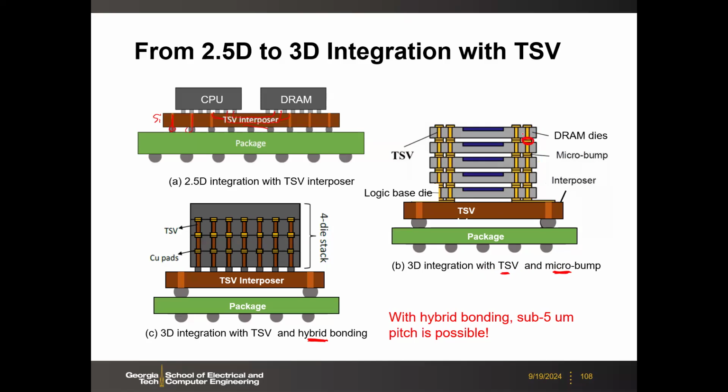If you have ever soldered your chip in your lab, you add some kind of alloy metal as a bond. Then you bond those chips. But in this case, this is micro bump. It's much smaller than what you manually do when you do the wire bonding in your lab projects. So this micro bump has dimensions of tens of micrometers, like 20, 30 micrometers. So it's really micro bump, okay? But still, you need to add some metal alloy here.